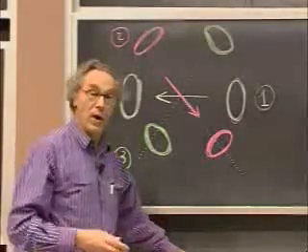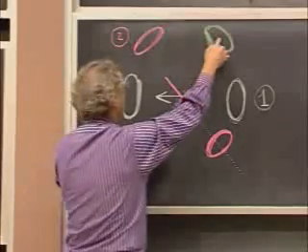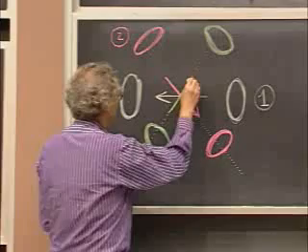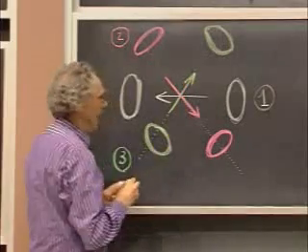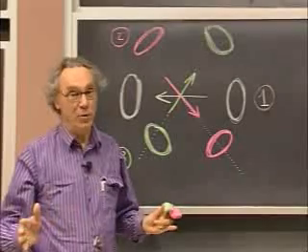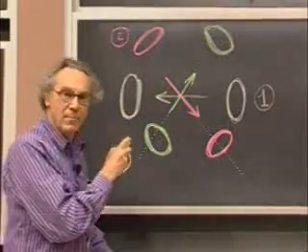And if we now look again 1/3 of a period later, when the current through loop number 3 reaches a maximum, then the magnetic field will be in this direction, and the vectorial sum of the magnetic field of the other two loops will also be in this direction. And look now what has happened.